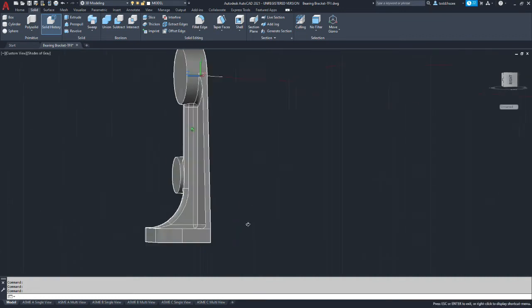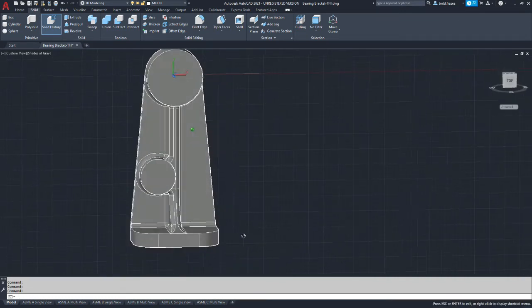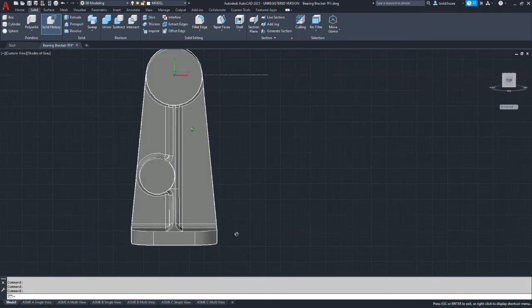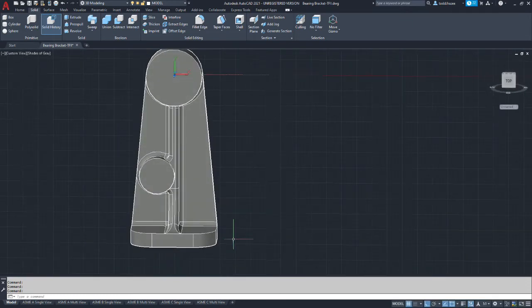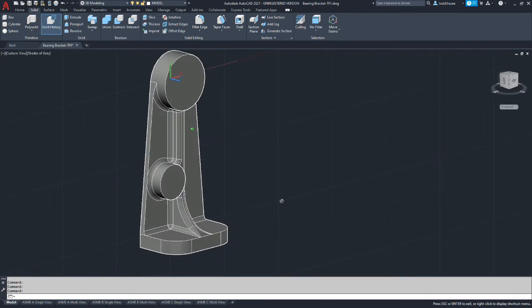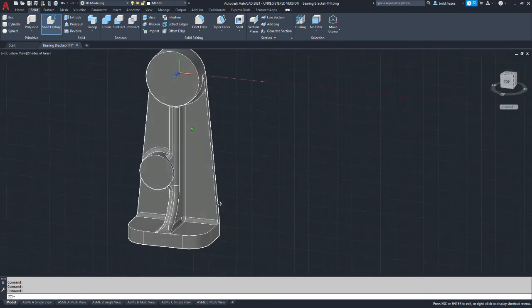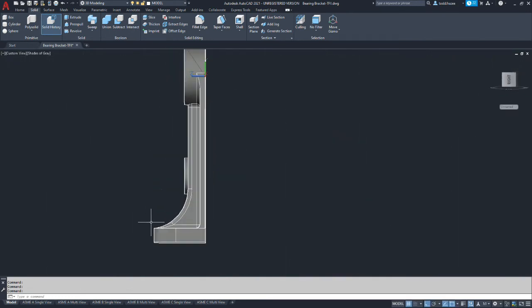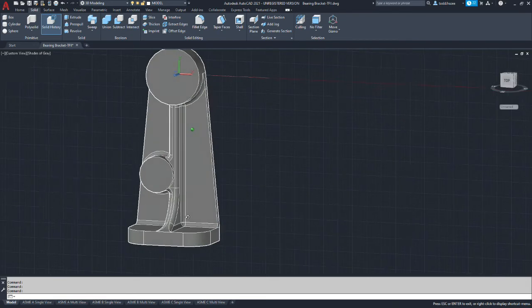So try to focus on the fillets that are going to describe the part in the views you're planning to do. In that context, even the fillets on this center rib aren't really all that critical. It's more the ones that you can see from the sides. So it'll be important that I can get this fillet here where my cursor is on the finished model.